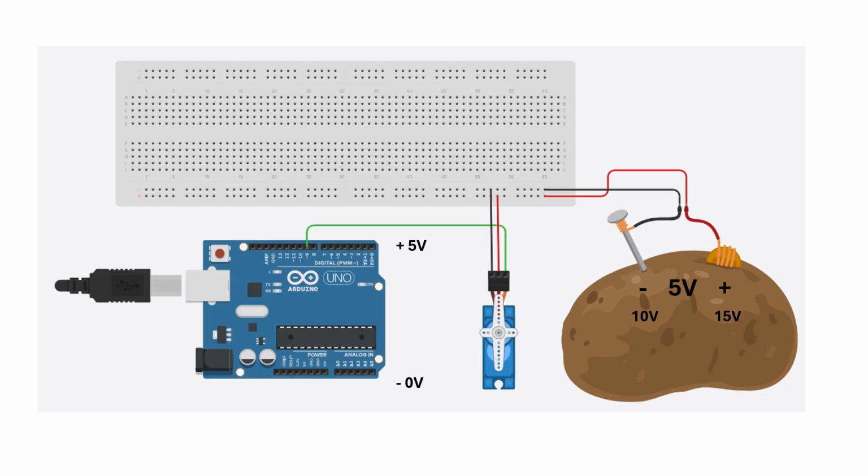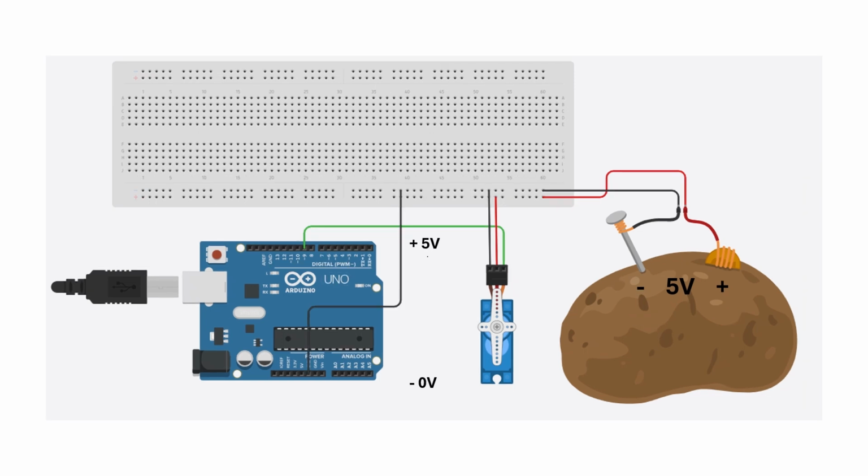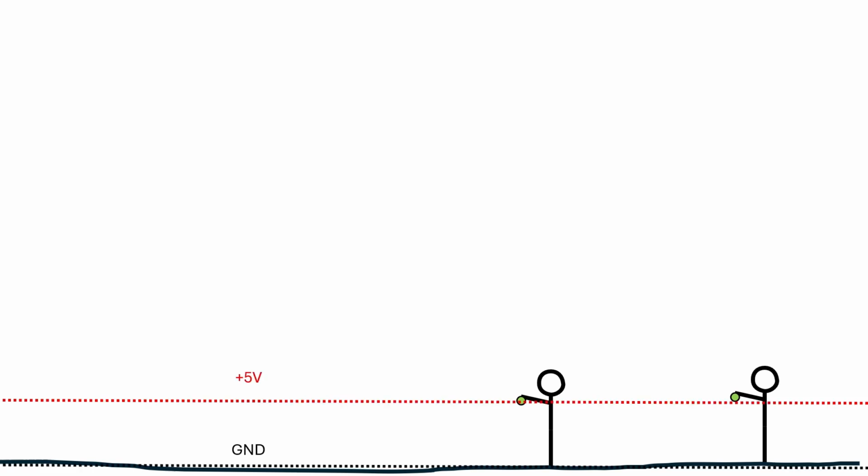So therefore, what I need to do is create this ground connection such that I link the ground pin of my Arduino to the negative terminal of my external source, and then I can force that external negative terminal to be at 0 and 5. And what that does is it brings the negative terminal of that external power source down to match the ground pin of the Arduino. Now, when I give my signal, it is at the voltage level that I required.